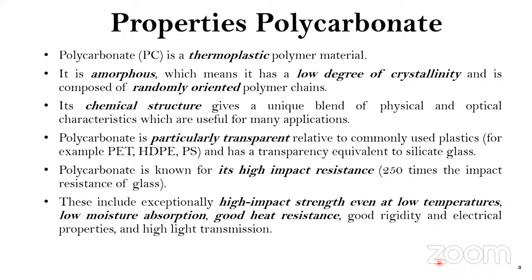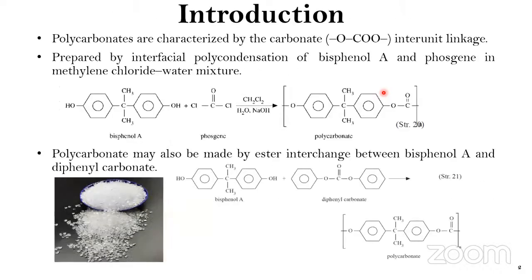First of all, it is a thermoplastic polymer, and it is also amorphous, because polycarbonates are quite transparent due to containing a high amount of amorphous content. That means if we have 60 to 70% amorphous, then the remaining 40% will be crystallinity. And this polycarbonate, as it is manufactured by the polycondensation mechanism, follows this.